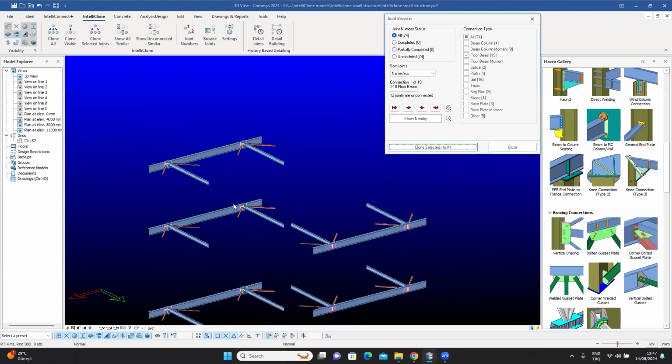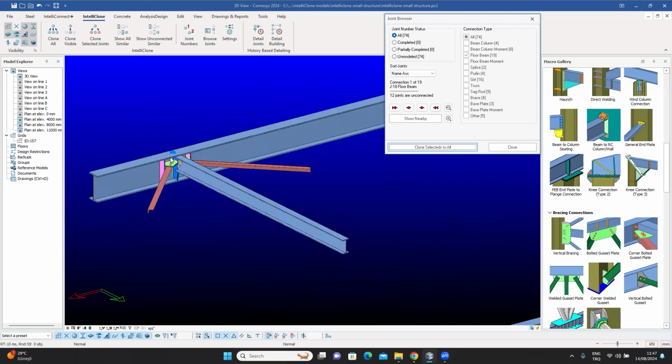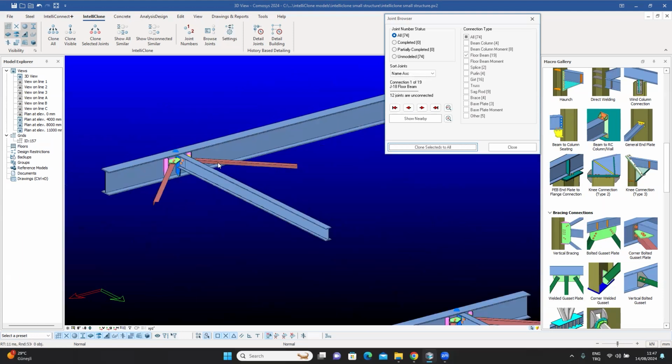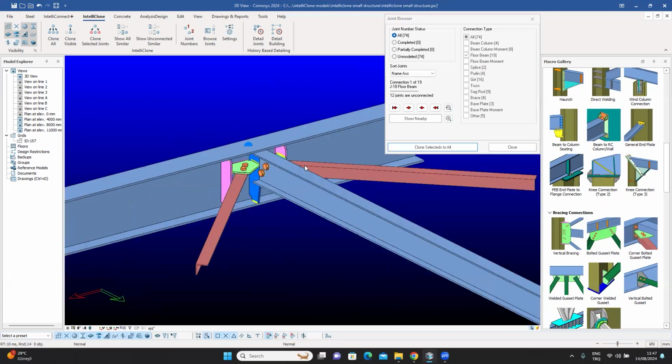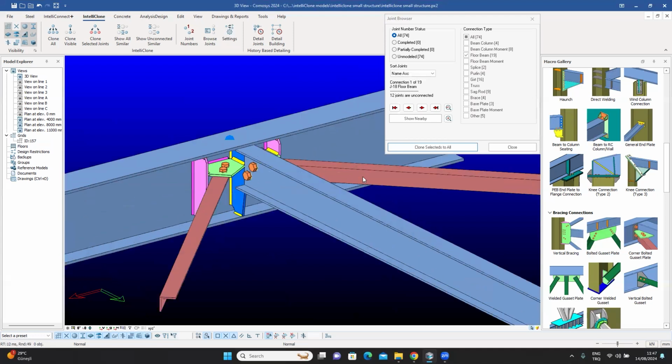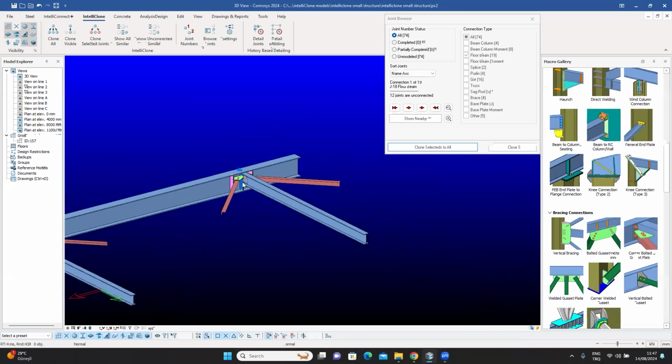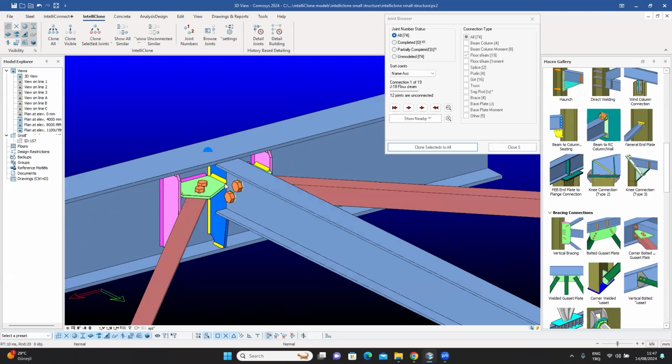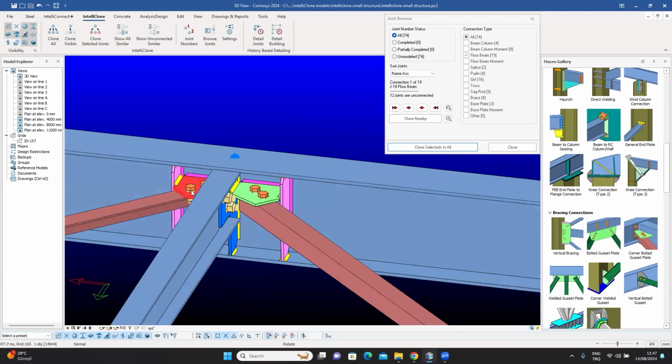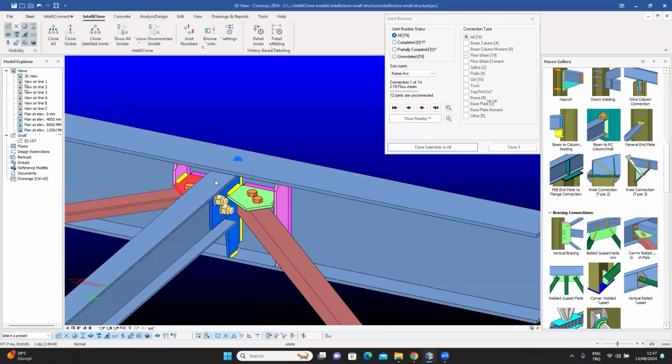Immediately, in all the 12 target areas, or rather 11 targets, because one of them is the one I sorted out myself. But the others, which I had not touched, their horizontal braces got rotated, lowered 80 millimeters according to the source, and the exact same connections were created in all the target areas.